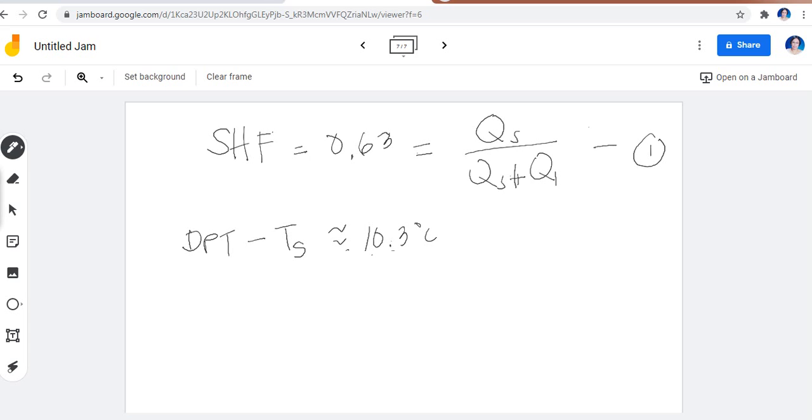From the line connecting your initial condition, I don't want to go to the psychrometric chart anymore. You have the dry bulb temperature and the relative humidity value. That pair leads you to the initial point, and then you have another two sets of values that lead to the final point.